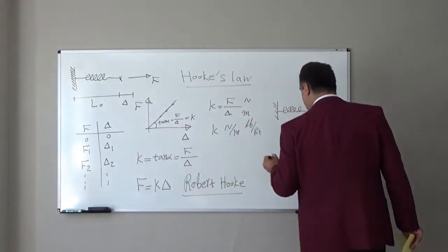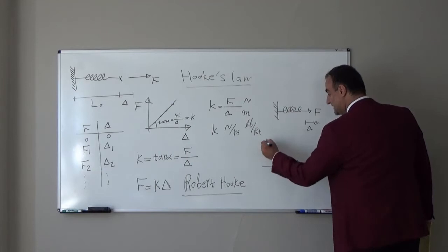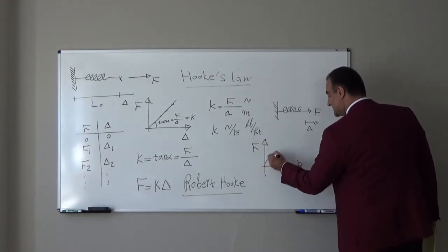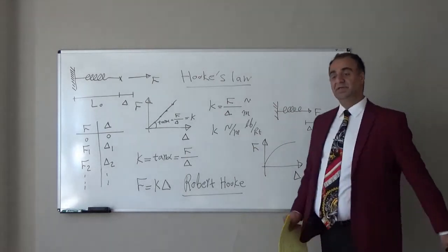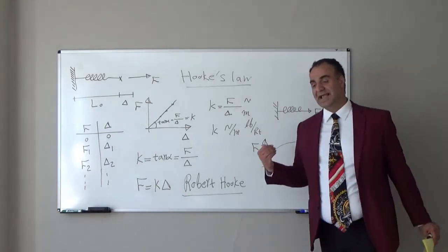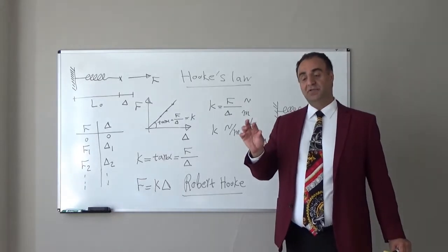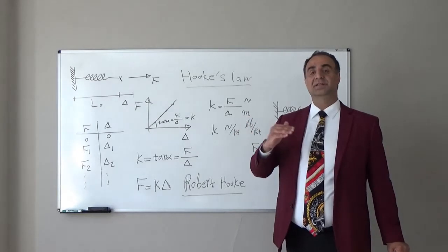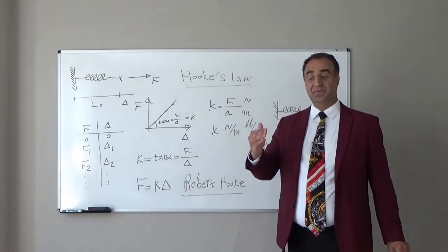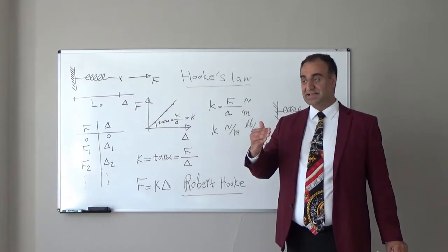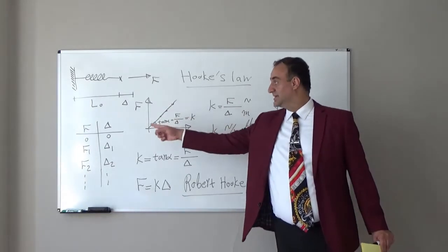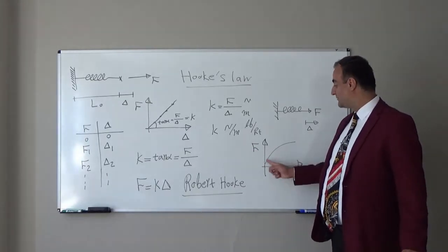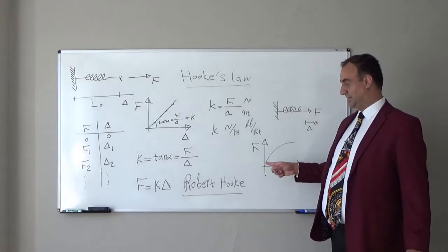And even in some materials, the relationship between force and deformation is nonlinear. In this kind of material, maybe the behavior is elastic, meaning you apply the load, you have deformation, you remove the load, the deformation will vanish, you don't have permanent deformation. It is still elastic, but it is not linear elastic. The deformation and force are not proportional. This kind of material we call nonlinear elastic.